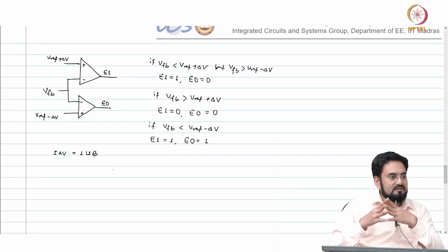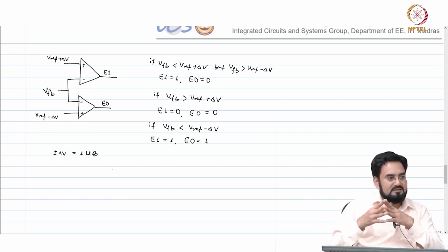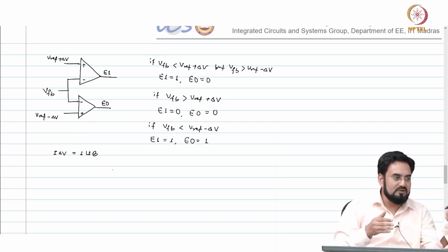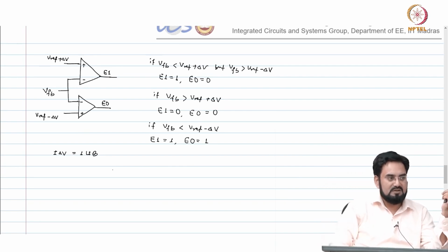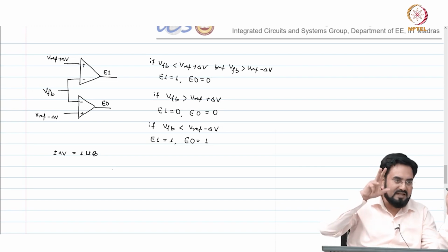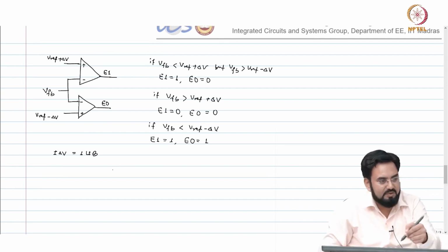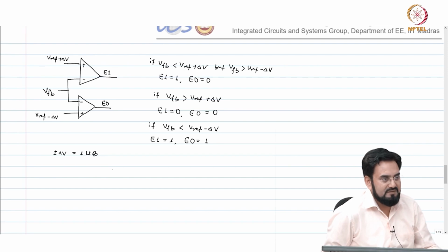Okay. Both 0 means low, so you have to increase it. The polarity you can decide however you want actually. You just have to make sure that when both are 0, you increase the code, and when both are 1, you reduce the code. Correct. And when it is in between, I freeze the code. So, now you have 3 levels. In fact, you have 4 combinations here, but you will get 3 levels. So, these are the 3 possible outputs you can have.